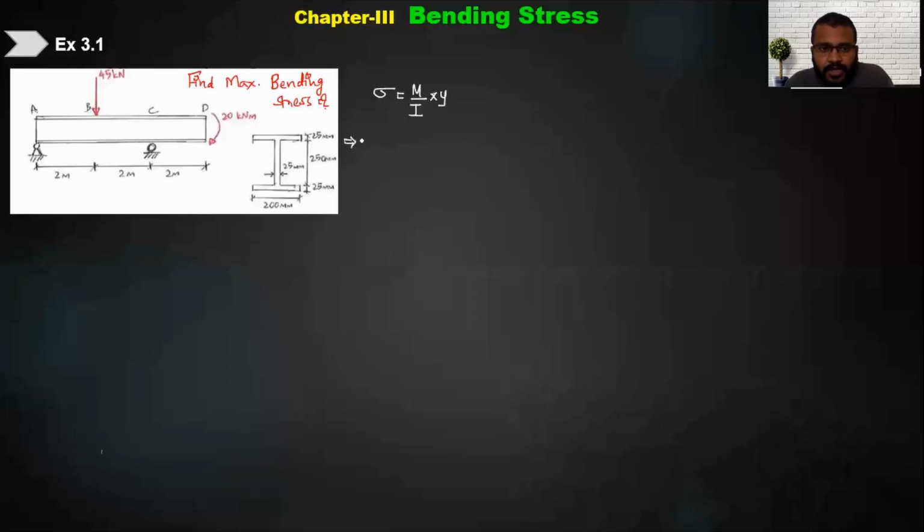So first step is to calculate I, moment of inertia of cross section about neutral axis. About neutral axis. Okay, how will you solve this? Is this diagram visible to all of you? If it is visible, I am directly writing down, because I know that the centroid is going to be at the center. We have already understood how to write down the inertia for this one.